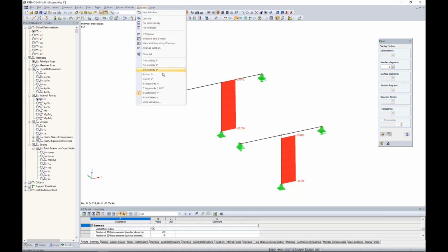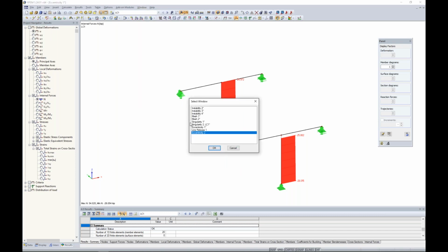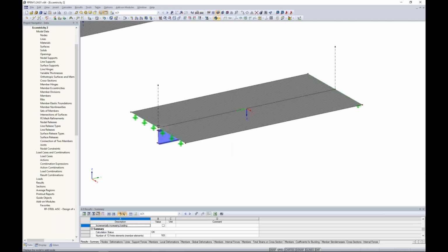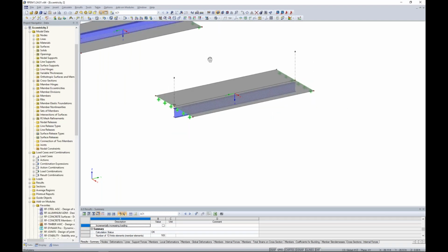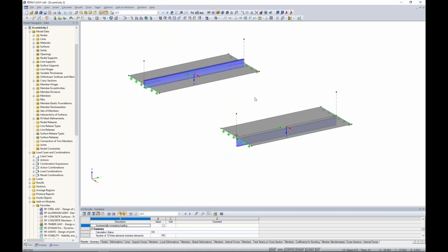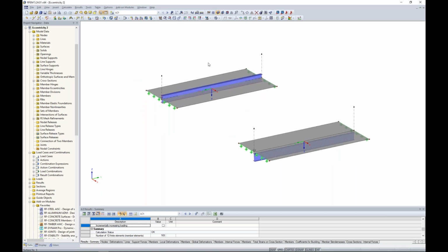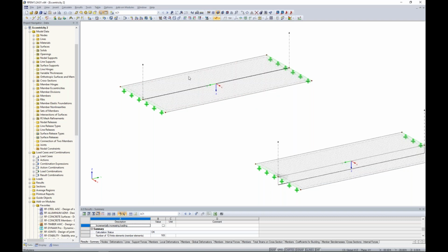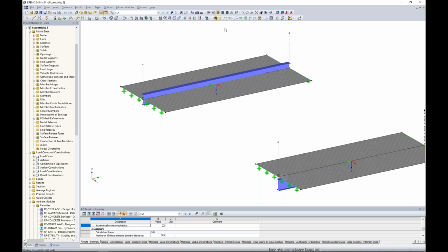So jumping into an additional example here, we'll go to the second example. Now there are scenarios where we do need to consider eccentricities for the full structural system. And a perfect example of this is composite behavior. So you'll notice my initial example and system up here, I have a concrete deck. I have also my steel member, and everything is just modeled with the center line. So I've applied that here. You can see those center lines just kind of lie directly within each other.